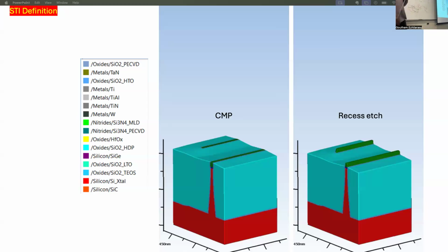So for the implantation process, when you're doping one side, you cover the other side. What material do you use to cover it? Oh, you can use either resist or some thick hard mask, because with resist you need much higher thickness to prevent the implant from going in. Otherwise, you can just use a thick oxide and nitride to prevent the implant from going in. Yeah.